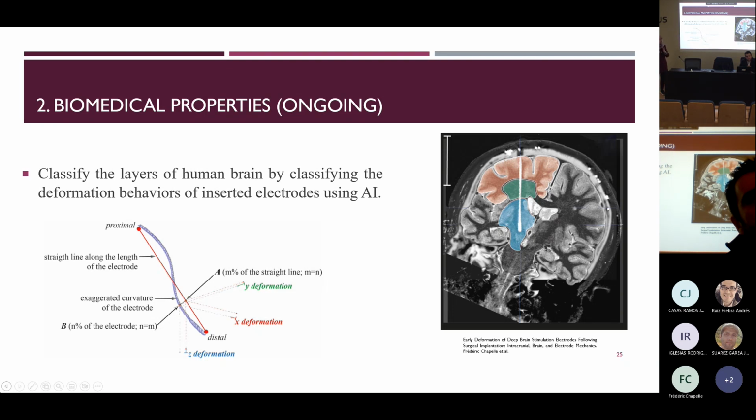It varies according to the dimension of the shape memory alloy. So I cannot say it's from X to Y, since it depends on the dimension that I have, the phase that I have, and the form. For example, I have one material that goes from -8, as martensite, to 68 as austenite. However, I have another one with a different dimension, which goes from 58 to 79. So the range varies, and these are only two examples. Maybe we have other examples with different ranges.